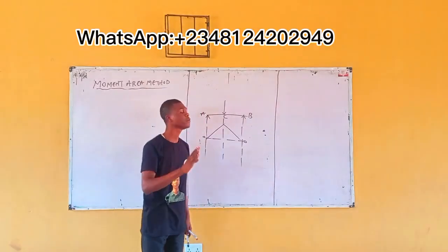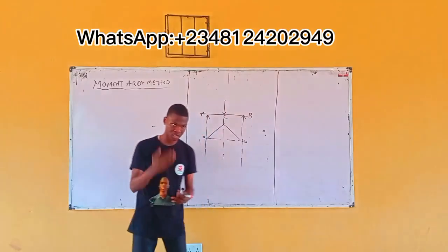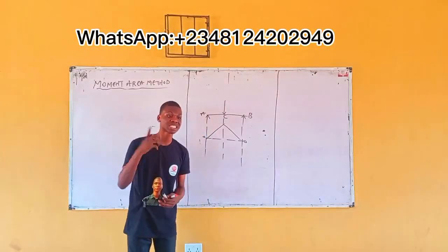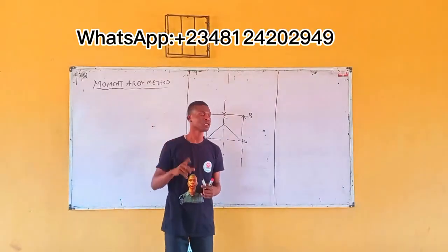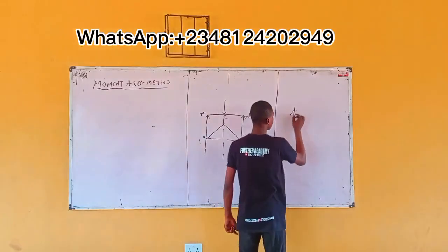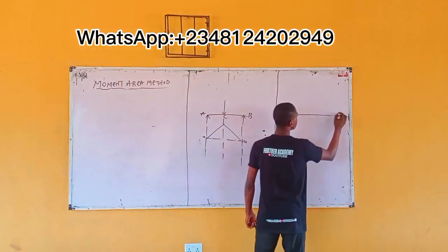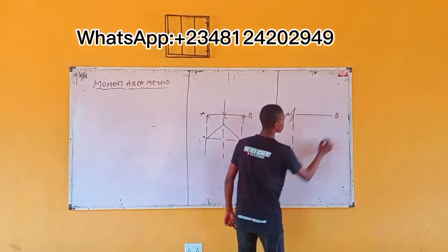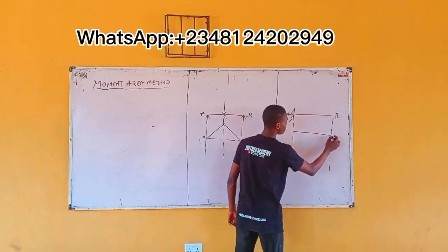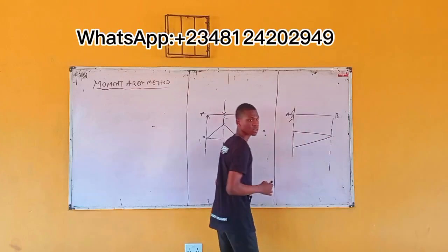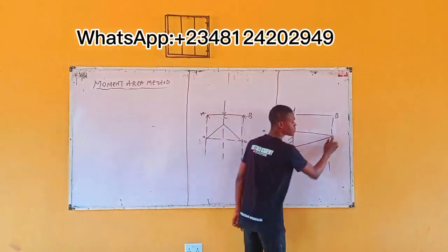That's if your beam, basically we have different types of beam. We have simply supported beam, overhanging beam, cantilever beam. For a cantilever beam, bending moment does not end with 0. You have a value at the fixed end. So this is what I'm saying. If this is your cantilever beam, this is A, this is B. So the bending moment of this cantilever beam, this is it. You have a value of bending moment here, while this place is 0.